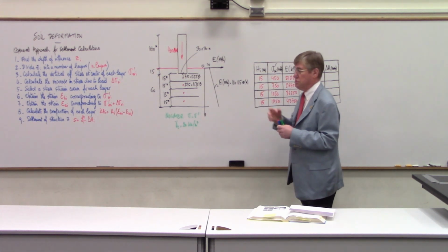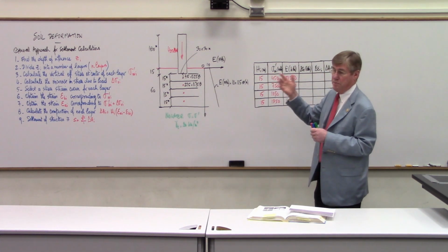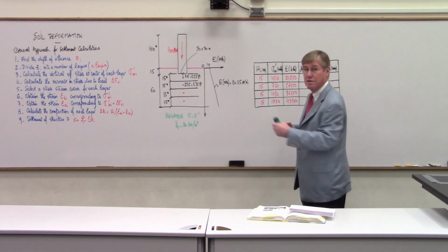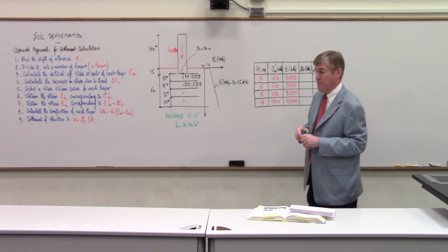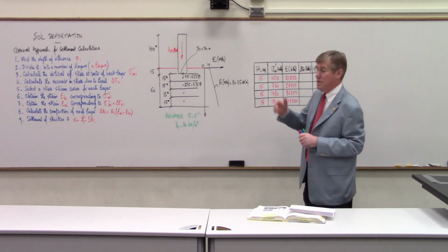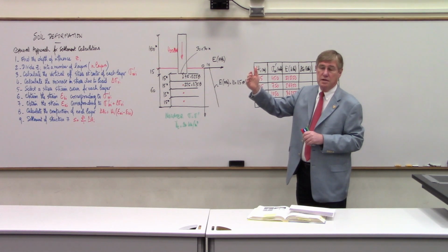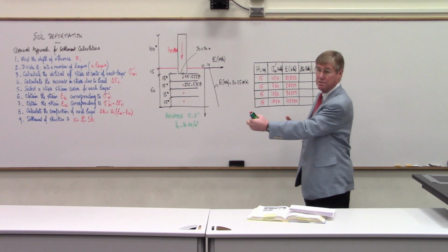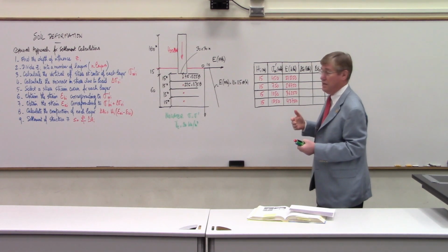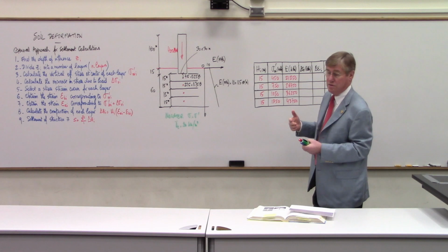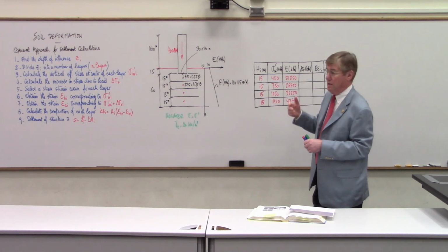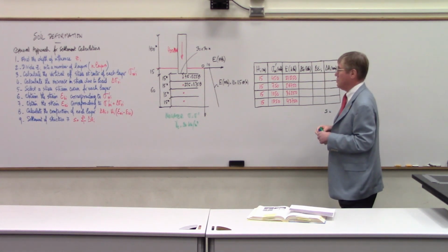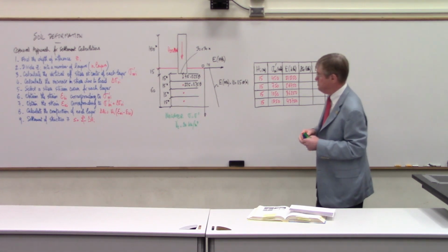Note that there's actually a scale on the left of that figure for square foundations and a scale for the strip footings on the right-hand side. So we would choose the left-hand side because this is a square foundation.